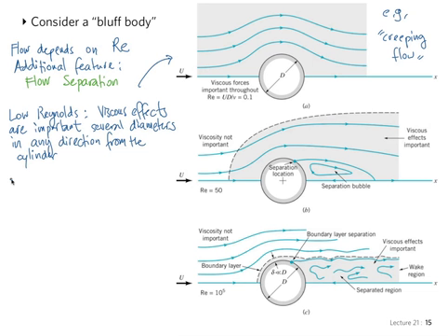As you increase the Reynolds number, then the confines of the effect of viscosity are going to be narrower and narrower. Basically, the boundary layer becomes narrow. Here is a situation with a moderate Reynolds number where already beyond a certain distance away from the object, there is no viscous effect. The flow doesn't feel the presence of the object.